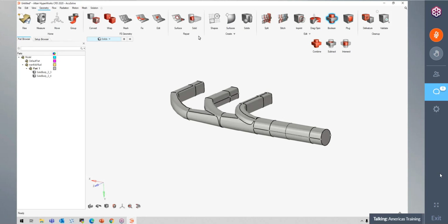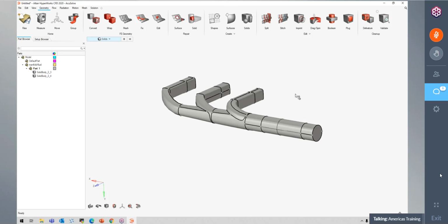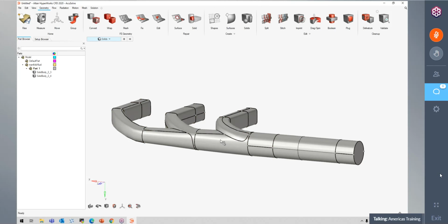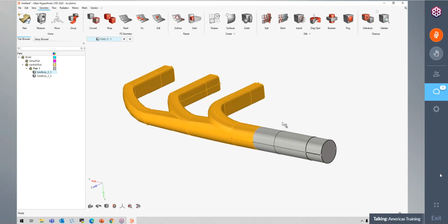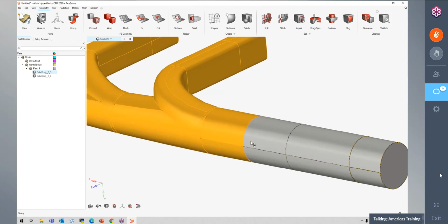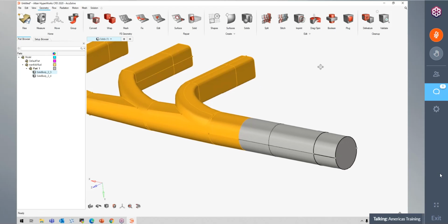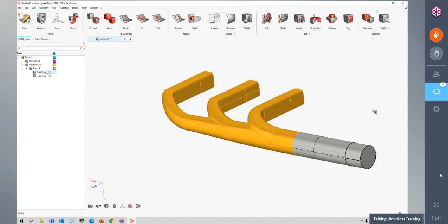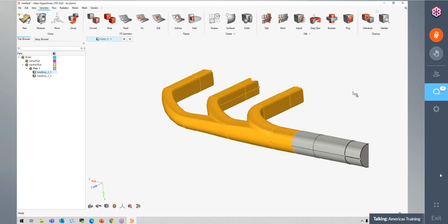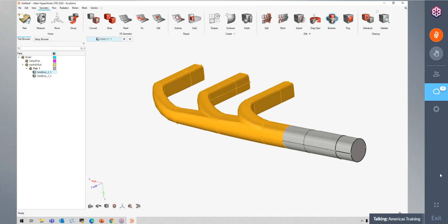So in some cases, you might bring two parts that are attached to each other. If I were to just mesh these two parts, so for example, as I mentioned before, I have two different solids here, right? I have this solid on the right and I have this solid on the left here. If I were to try to generate a mesh, sometimes if I were to just import this with two different parts in it, it might not know that those two are connected and the meshes might not line up. So one thing that's good to do sometimes is to make sure that those two are attached to each other or connected. And one way that we can do that is by using this Boolean tool.